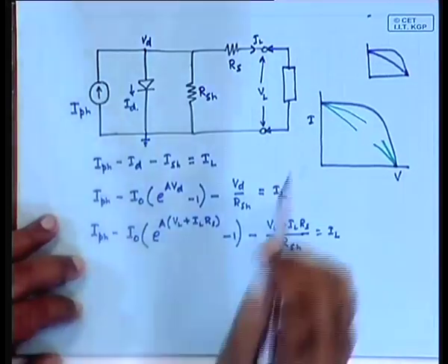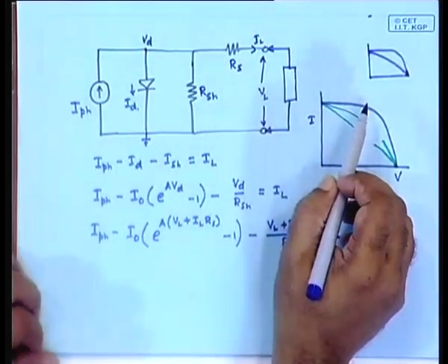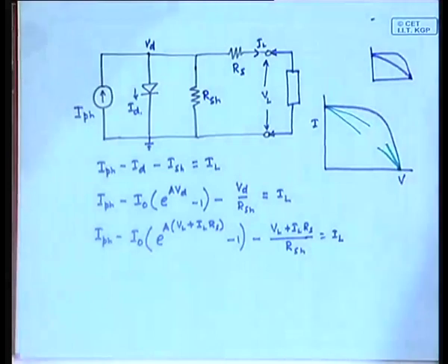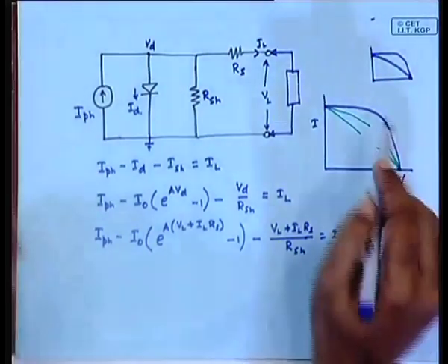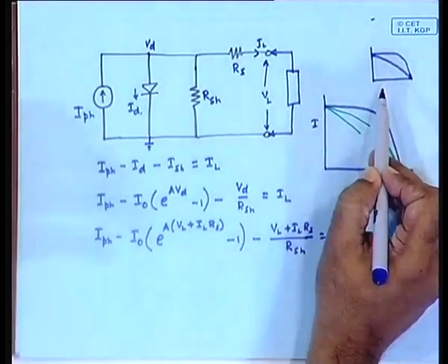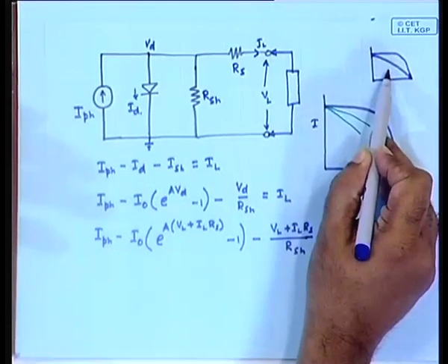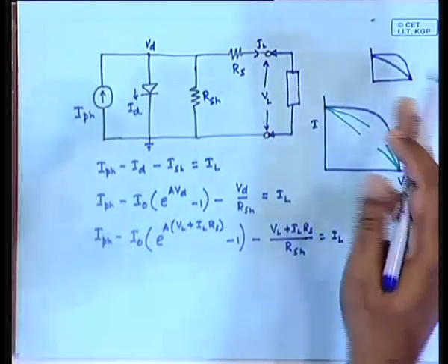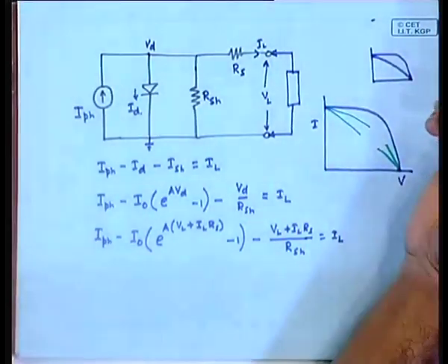Notice the VOC and ISC remain the same, well, almost, yet the power that you can get out of it goes down because the fill factor goes down. So, if you still specify it, you will say that it still produces the same open circuit voltage, and often people do not understand this. If you measure it, the voltage is still the same, yet the cell is not as productive, and this is also true for badly manufactured panels.